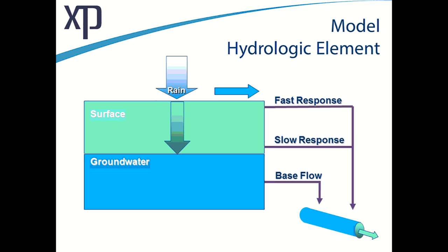And the last thing we want to talk about is base flow, which is infiltration that's getting in. Typically it's fairly constant and maybe seasonally varied. For example, here in the northwest in the Portland, Seattle area, you'll find that a 1-inch rainfall that would occur today has a completely different response than a 1-inch rainfall that would occur, let's say, in August, where most of the water would soak in. Today, more things are saturated and you get more runoff than you would in the summer.